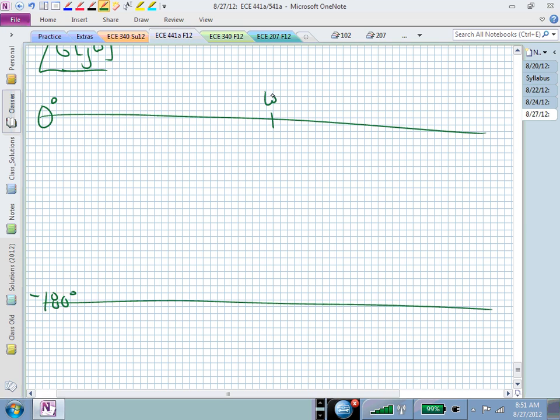And what happens? A decade before I start transitioning, a decade after, in our approximation, we're done transitioning, and so now I'm here, then I go through minus 90 degrees, and then I'm there at minus 180. So this is supposed to be minus 90 degrees, and I'll line it up. That's supposed to be omega equal 10. That's my straight line approximation.